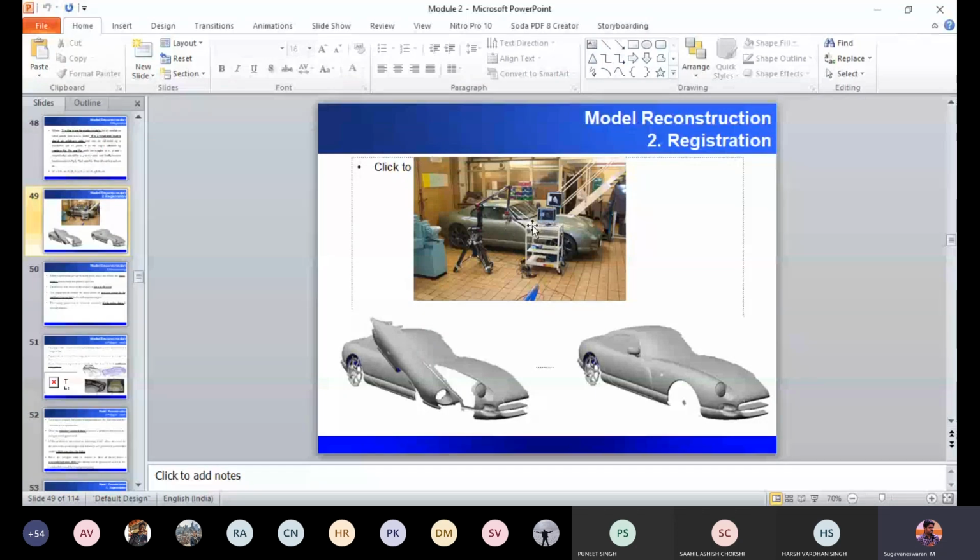In non-contact reverse engineering, we cannot capture the entire surface in a single stretch. If I want to capture my face, the profile of the cheek and everything will get captured, but the nose surface, which is parallel to the camera, will not get captured in the three-dimensional part. So in that case, I have to rotate the camera for some degrees. Then I can capture the nose surface.